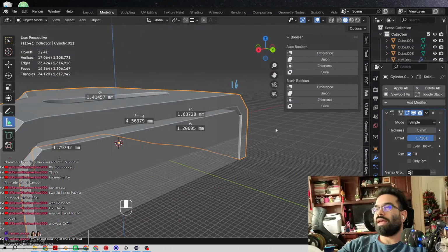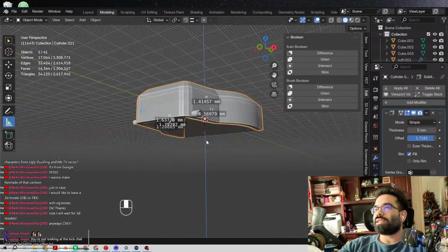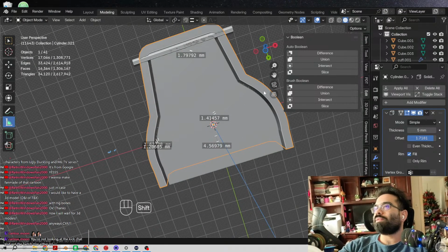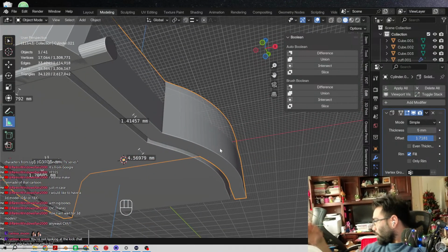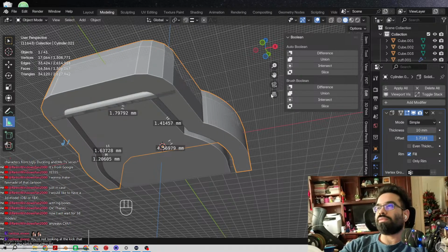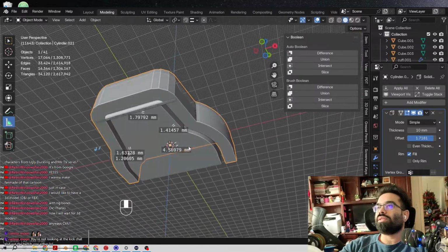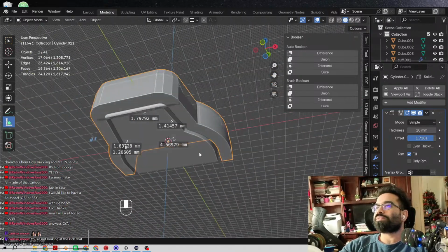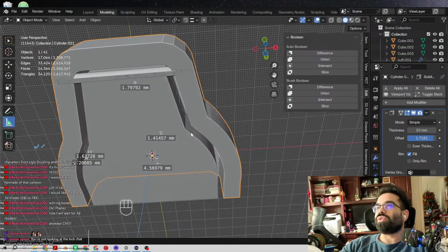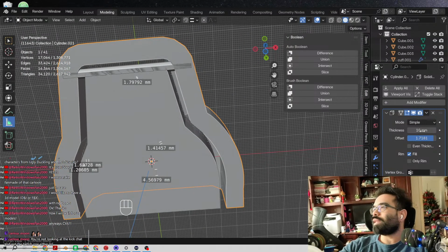Okay, and the reason is because there's going to be a bunch of extra plastic over on the outside of this, and to flatten it out, it's probably better to have something that's thick. Originally I had a thin version, and I don't have my prototype here, but we're going to go ahead and just make it thicker. You're probably wanting to do that for a box. It's up to you. It depends on what you're going for. But we're going to keep that offset there, and let's just double it first, right? And you see how it made it thicker. It made it a bunch thicker, which is what we're going for, and I like that. That's not bad. This is just going to be used to squish that plastic down over.